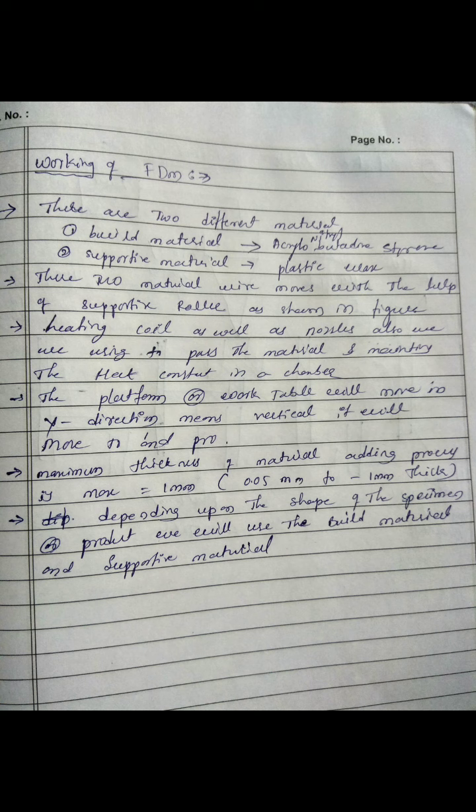The hydrochloric acid solution reacts with the plastic wax within a short time. Then the plastic wax is discarded, removed from the ABS material. Finally, the product made from the ABS material is left in the container.